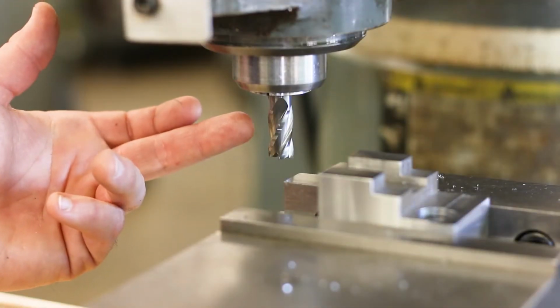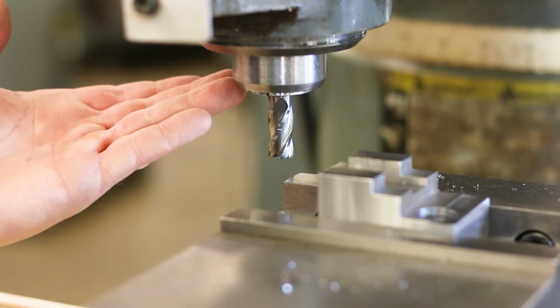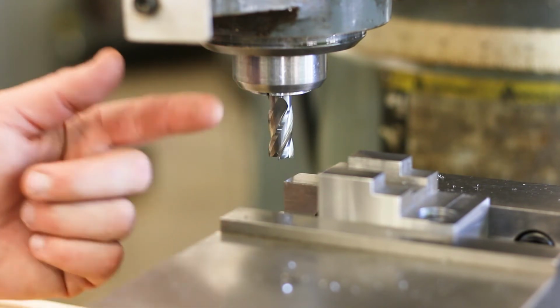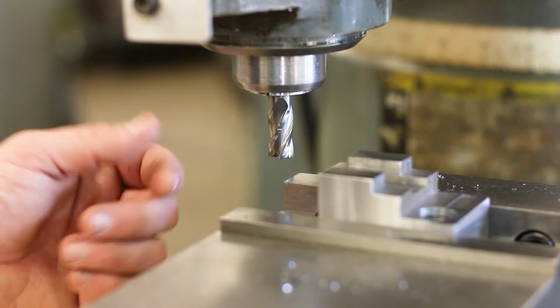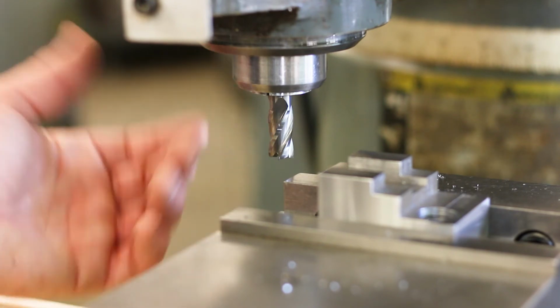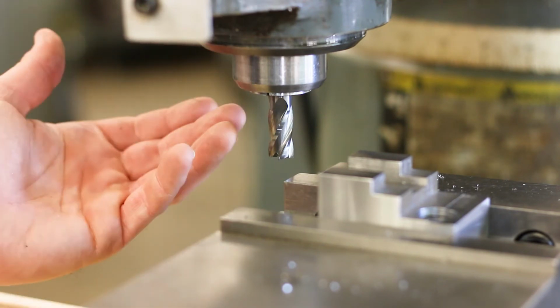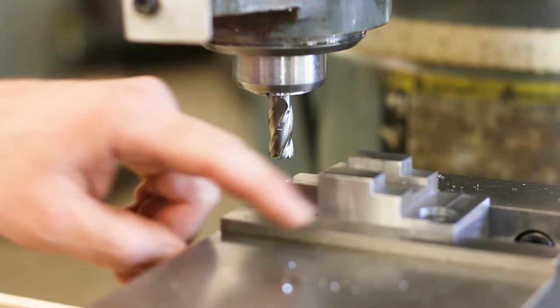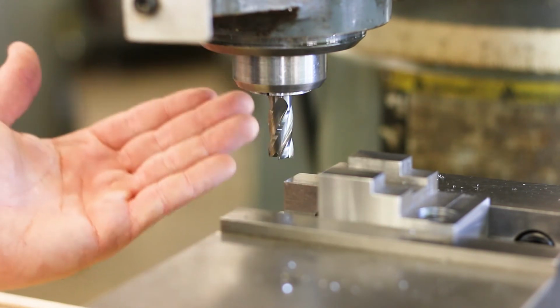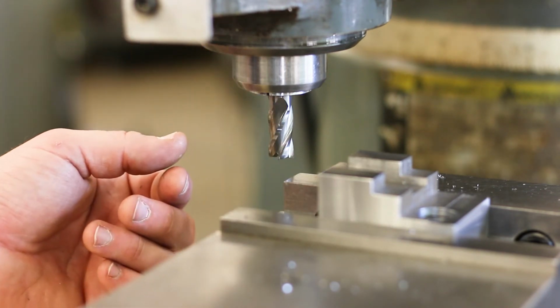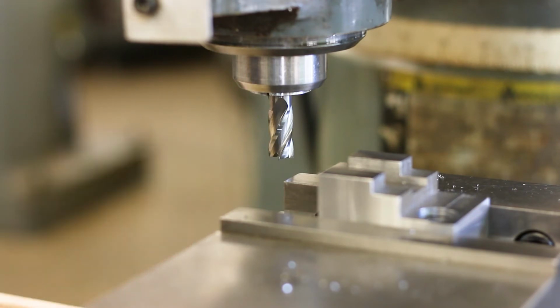So here's what I'm going to do. I'm going to go ahead and raise the knee 14 and a half thousandths and then take another cut where I just took a cut, and then I'm going to forget about the depth setting. That way, every other pass that I take on this step right there is going to be at that depth, and I'm going to get my 750 thousandths. So here I go. That's 10, 14 and a half right there.